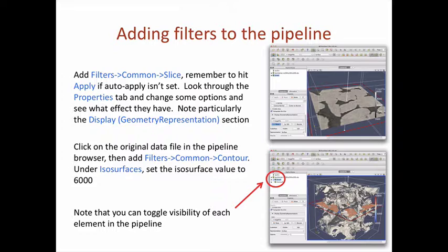So when your resolution is 0.3 millimeters, then it's plus or minus that. Let's say you wanted a 600 micron pore, you're going to get anywhere between 500 and 700, and that's not good enough for our purposes. Also, apparently a lot of microporosity is created near the surface in the process. So if you do MICP of that pore, you're going to get the 600-ish micron pore, and you also get some smaller pores on the side that are essentially microporosity of the material from the printing.